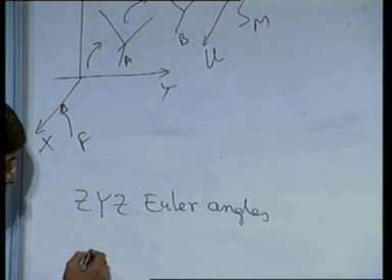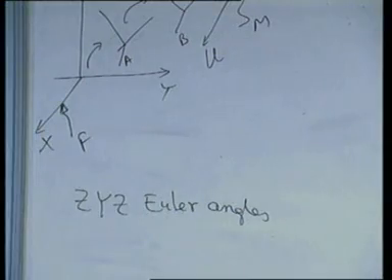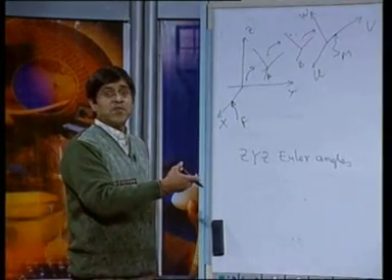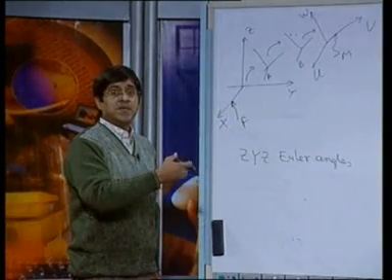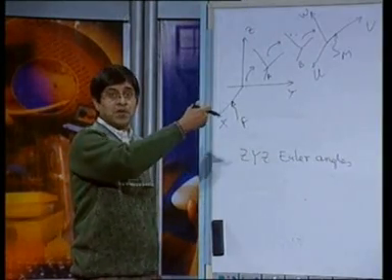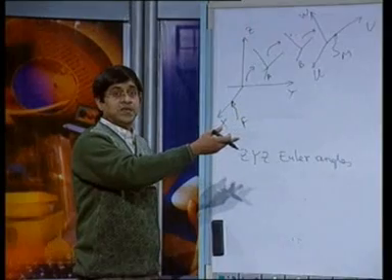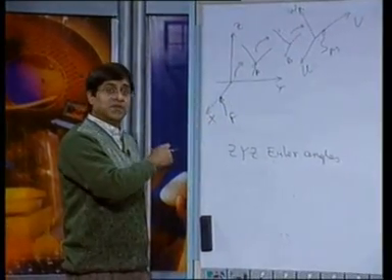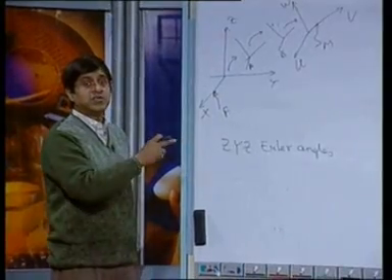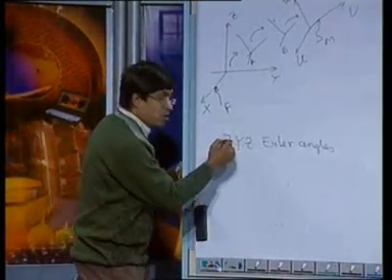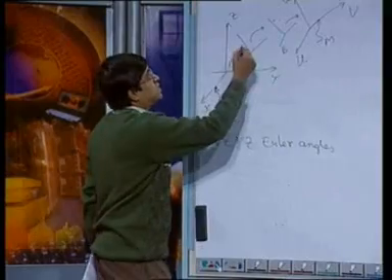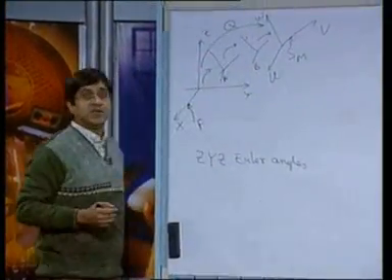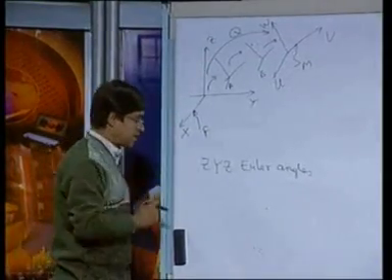Now, for getting the expressions, we have just seen that orientation is represented in the form of a matrix, and that matrix is required to transform the coordinates of a point represented in a moving coordinate frame to the fixed coordinate frame. So, that matrix we require all the time. So, now we are interested in that matrix, what is the matrix relating these. So, this Q matrix we are interested in, as we have found out in the earlier case.